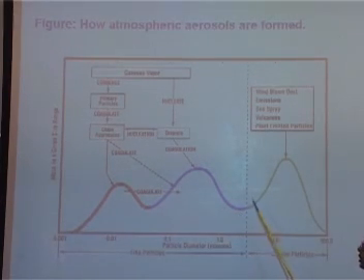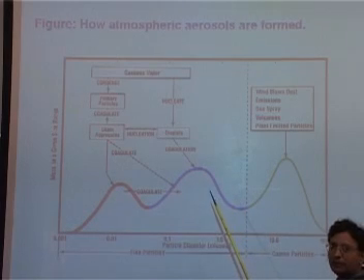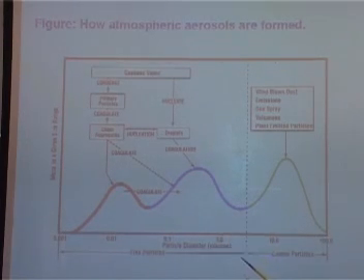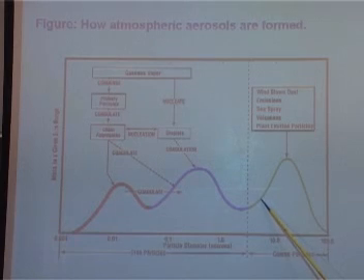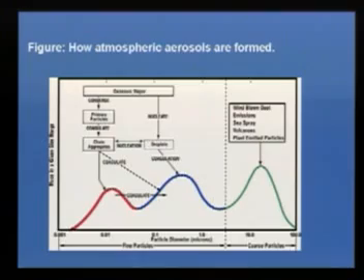So there are distinct things you will get in the atmosphere. Therefore, all the standards that we have been talking about are for particles with PM10. Why PM10? Although you will get the size distribution like this, beyond that the air pollution effects are not so significant, because these are mostly stopped at your nasal cavity and things like that. PM10 can go to the upper part of the respiration system, but these particles become very dangerous.